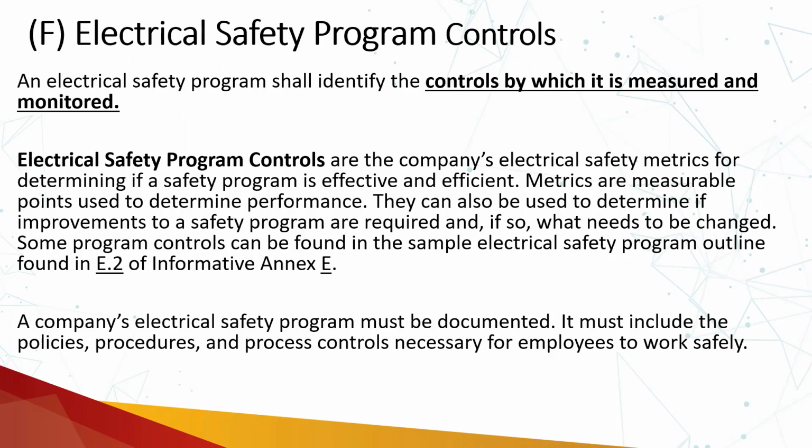But after implementing the electrical safety program in the organization, those energized tasks have reduced by, for example, 70-75%, and the remaining 20-25% of tasks are justified and authorized. For those remaining tasks, we see that the proper procedure for justification and authorization is being followed. So we can apply different types of controls in order to measure whether our electrical safety program is effective and efficient or not.